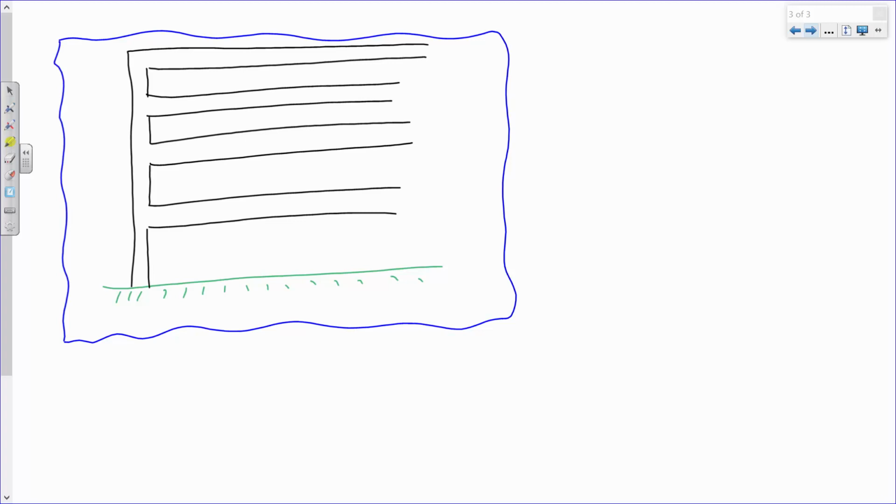Okay, so let's say I have a building and it's got 4 different stories, like 4 different floor systems. So if I'm looking at this column segment right here, it's going to be seeing 30 kips of compressive force, right? But what about this column? How much force is in the column on that story? That plus the weight of the previous. Exactly, so this one's going to be seeing 60 kips. What about this one? 90 kips. So, just from this really, really light load, you could easily get 120 kips of load on the ground.